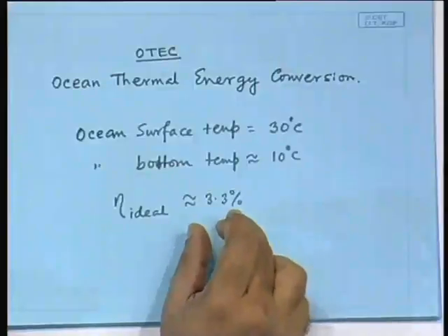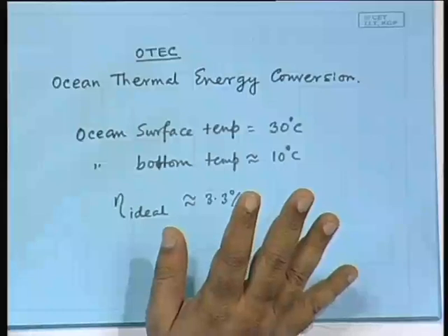The question then is how to do the condensation? It has to be at a very low temperature. So, that temperature is the ocean bottom temperature. So, somehow you have to pump water up from the ocean bottom to use it in the condenser, right. In that case, what become T1 and T2? T1, as you know, is the temperature of the steam at the highest point. T2 is the temperature of the water at the lowest point in the circulation of the principal fluid. In that case, these two are the temperatures. So, you can reach an efficiency somewhat close to this, 2% is more or less average.